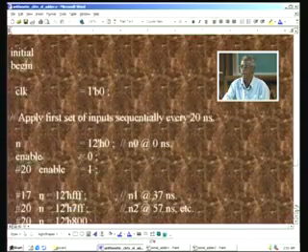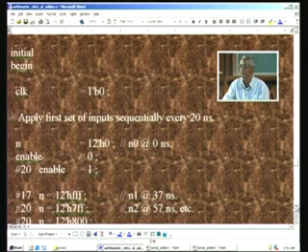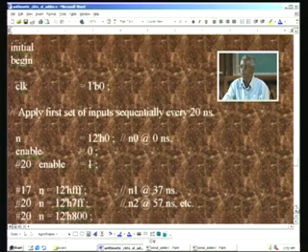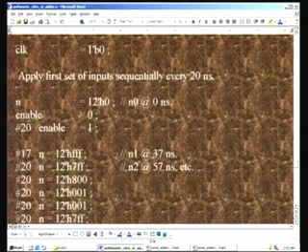And the next thing is we initialize and apply the actual stimulus or the actual inputs. For example, clock is initialized here, and the first input n naught value is 0, and we are going to enable only at 20 nanoseconds here, and then apply all the other inputs. For example, n naught is here, and this is n1, n2 and so on in this order.